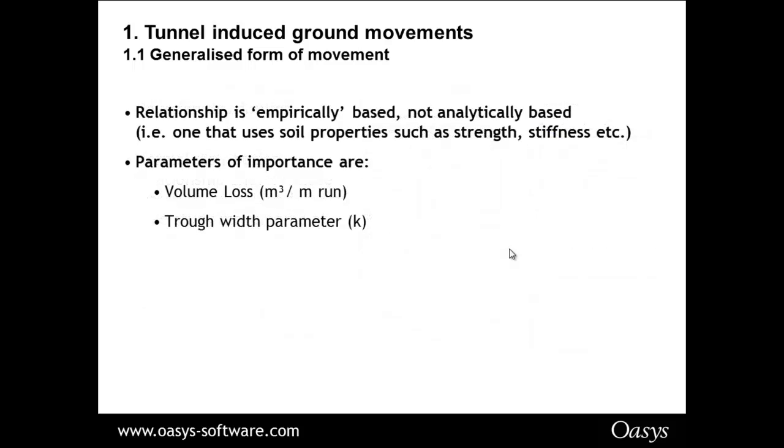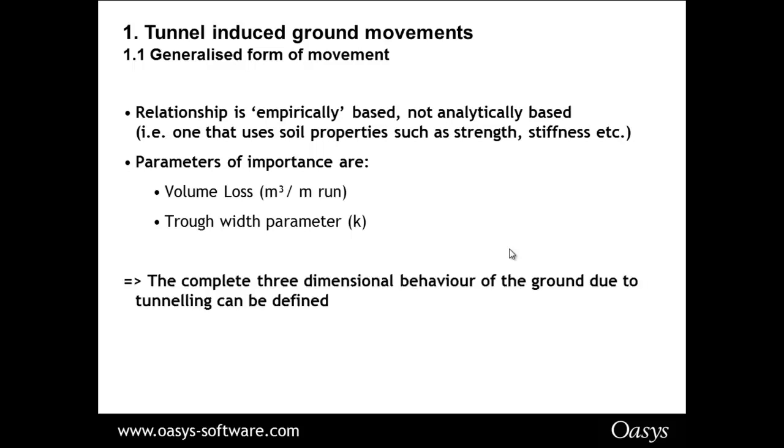In terms of the actual analysis, as I mentioned, it's empirically based. If it was analytically based and you needed to do a finite element analysis, you would have to understand the soil properties, the strengths, the stiffnesses, and various other things. But for Xdisp, you just really need to know your volume loss and your trough width parameter, and then you get complete three-dimensional behavior of the ground due to tunneling. So it's quite a powerful program based on very simple principles.